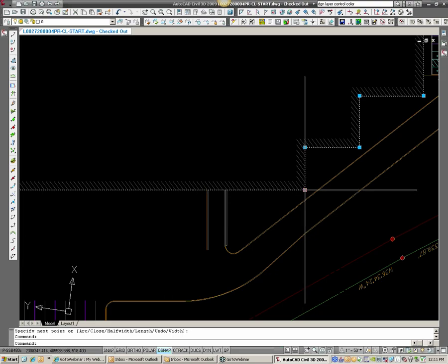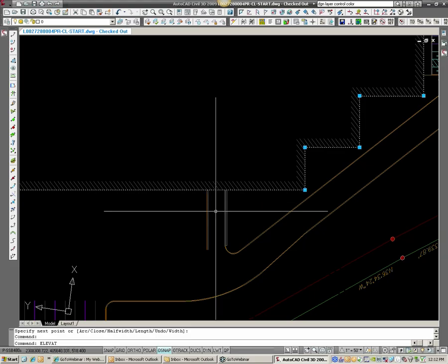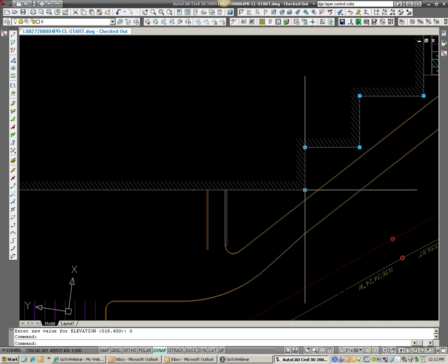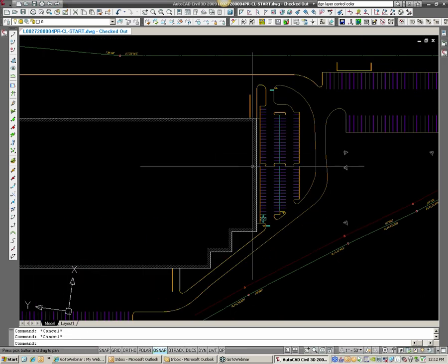And if I hover over one of those nodes, you can see down here in the elevation coordinate display here, if I hover over the nodes, they remain on 51840. If I change my elevation back to 0, grab that line, hover over it, it's going to be 51840. Okay? So that gets my building first floor perimeter.